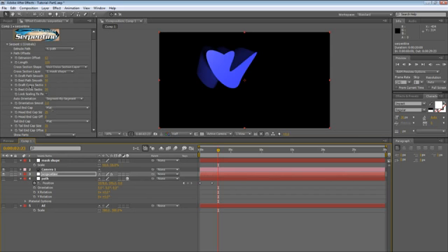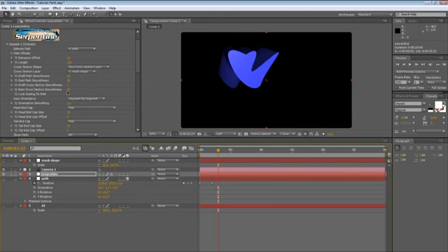From my experience, I wouldn't touch the draft. I would keep it at 20. I would turn the best path smoothness, there we go, to 100. And anything above 100 doesn't really make a lot of change, although you can crank it up more and more, but it just slows things down, and 100 seems like a really good number to work with. So we spoke about all of these. We left out path offsets. We'll talk about this later.